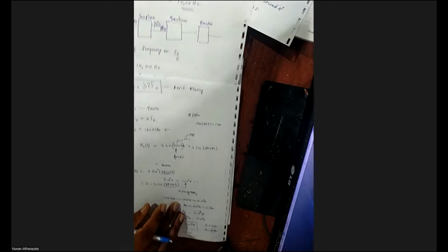Yeah. The simple idea behind this is if you simply refer to the sinusoidal signal, we have this positive half cycle, then negative half, then positive, and then negative. If you make it squared, these negative halves are simply pushed into the positive direction. So then automatically the frequency gets doubled. Did you get the point? Yeah, I get the point, sir.